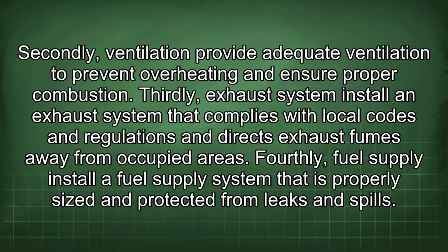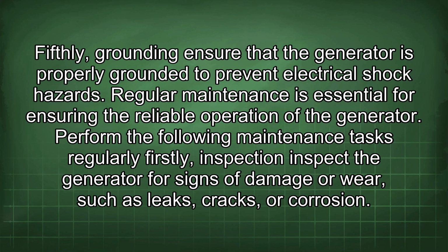occupied areas. Fourthly, fuel supply. Install a fuel supply system that is properly sized and protected from leaks and spills. Fifthly, grounding. Ensure that the generator is properly grounded to prevent electrical shock hazards. Regular maintenance is essential for ensuring the reliable operation of the generator. Perform the following maintenance tasks regularly.